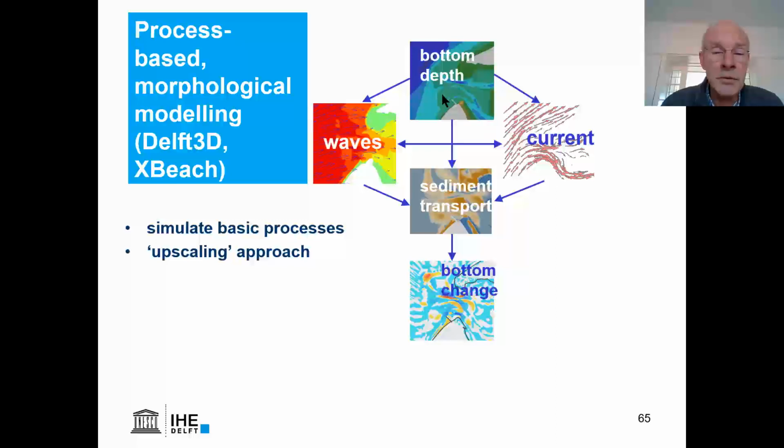Based on this bathymetry, you can do wave simulations and current simulations. And these two interact with each other. The waves impact the current and the water levels impact the waves. And together, they create a sediment transport pattern that varies with the tide and with wave conditions. And that leads to bottom changes. And well, in the old days, we would stick to that, but nowadays